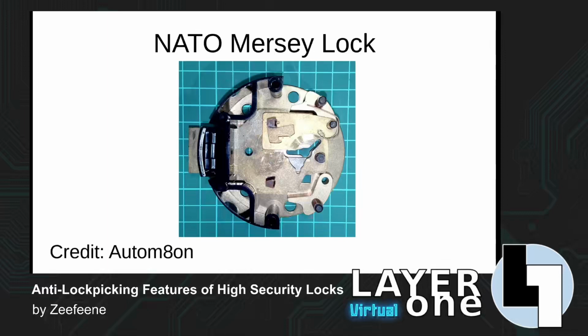We have this kind of strange element here with a nose and a pivot, which is this portion here. We can see the corresponding one up here as well. That's the pivot for it, and there's the nose on the end of it. And here we can see that there is a pivot for the levers, and the pivot for the levers is inside this pivoting portion itself. So when we apply tension to the lock conventionally, what happens is these two stumps, which are attached to the bolt, just move nicely into the gate when we use the correct key, and the lock opens totally normally.